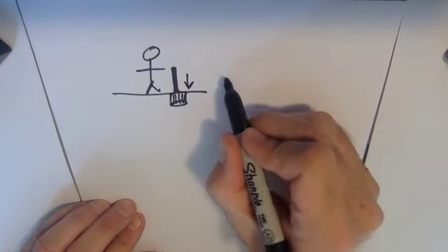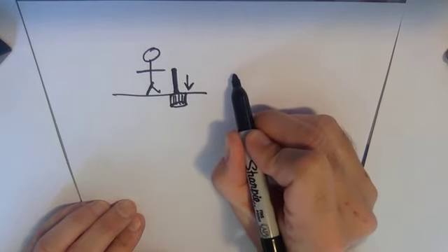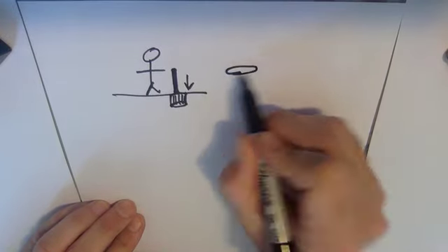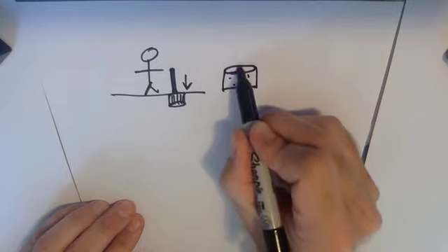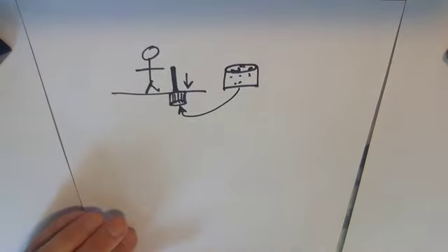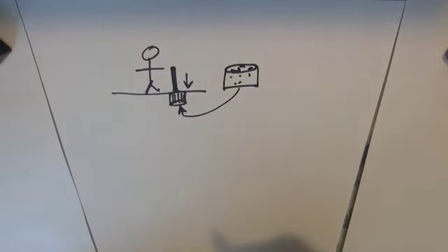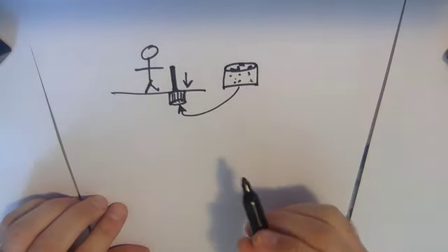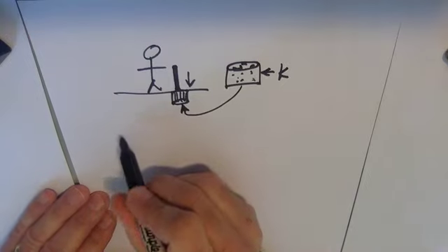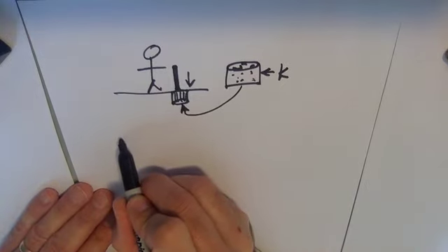You pull it out, and you take it back to the lab, and you take it out, and what you have essentially is a section of material. This is all the dirt and everything that was fitting inside this little open hole when you shoved it down into the ground. And you put that thing into this constant head permeameter, and you can measure the hydraulic conductivity on this bulk sample.